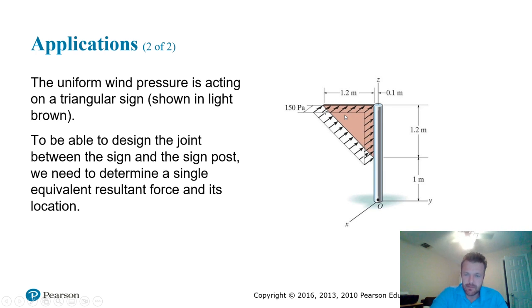The idea is, if we look at this distribution, first note that the units of these little force vectors are in units of Pa, the abbreviation for Pascal, which is the SI unit for pressure. If I were to talk about how much force is being exerted at a particular point, remember that when you have any kind of density, including pressure, where the density is expressed by a function, as we'll see in the next slide, and you want to determine how much force is acting at a particular point, you can't just evaluate the density function at that point. You actually have to use the concept of calculus, of integration. You have to sum the density over some very small area near the point of interest, and that's what allows you to determine how much force is being exerted at that particular point.